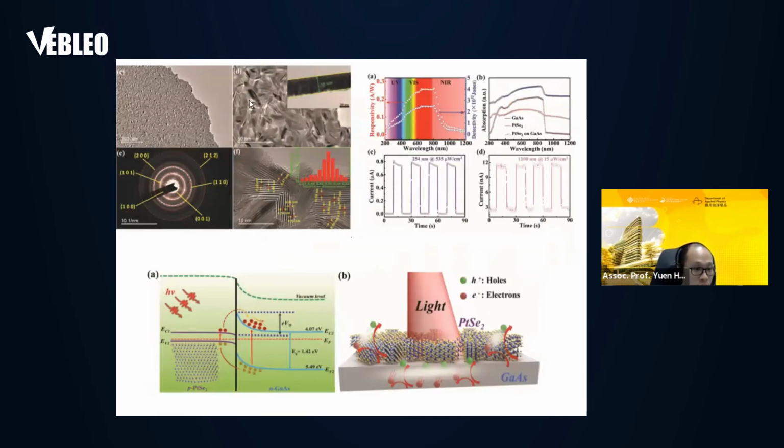As you can see from there, that was done by the metal sputtering technique. We're actually using several techniques to make this absorber, but for this particular one, we deposit a polycrystalline structure. As you can see, some of them are actually vertical standing. This vertical standing might have some effect on the absorption spectrum. So that's why we characterize our photodetector with respect to the spectrum response, and we found that this material is capable of having a very broad absorption spectrum, from ultraviolet up to 1.2 micron.